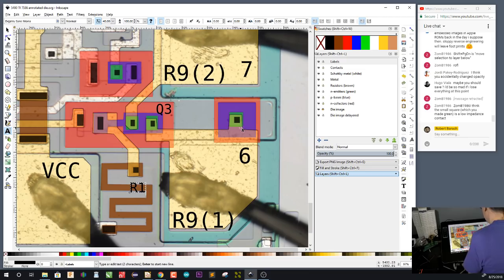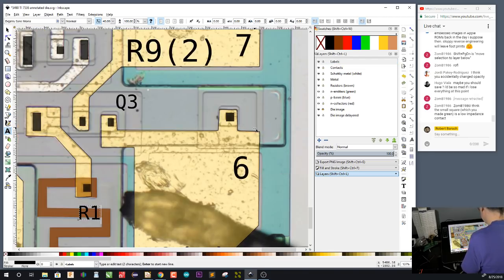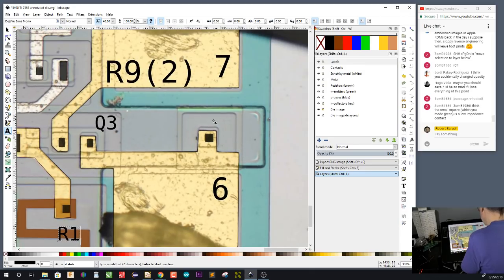Well, okay, so the square here, let me just hide all these regions. Okay. So if this square is a low impedance region, then let's ignore it. And that means that this is the anode, which is negative, so it's got to be N. That would mean the outside would be P, and then the outside of that would be N, which we know to be incorrect because that is the substrate.